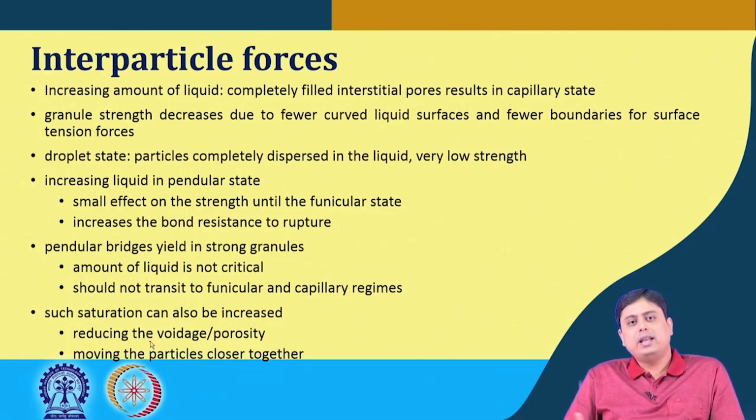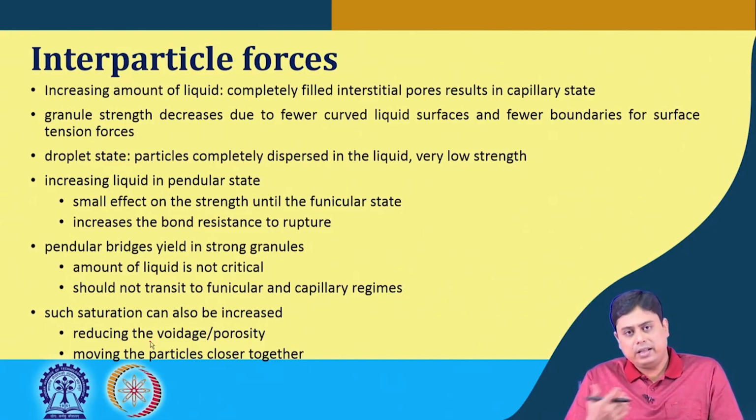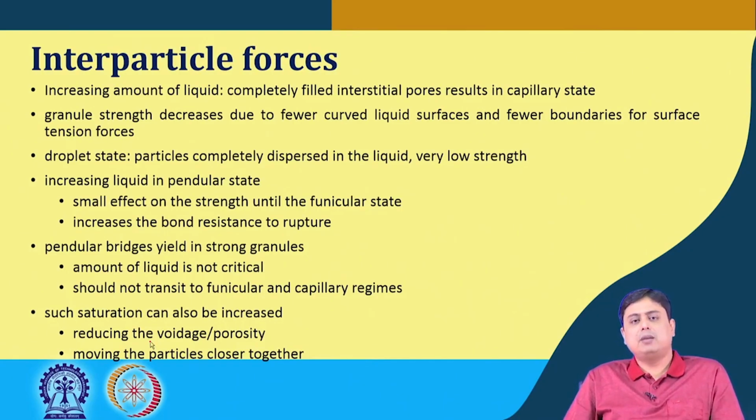So, as you increase the liquid amount, it becomes the capillary state. You further increase the liquid amount, it goes to the droplet state. Now, in the droplet state, the particle is completely dispersed in the liquid. So, quite obviously the strength of this bond, of these forces, is very low.